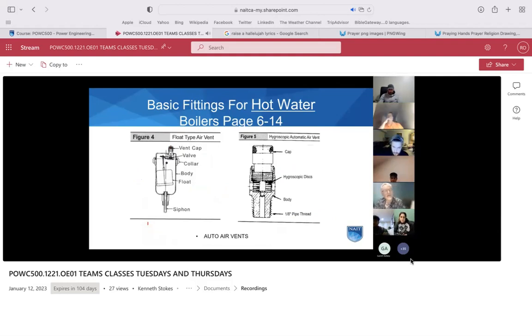So another thing in a hot water system, heating of hot water and moving it around and having it in an expansion tank with an interface with air. This water is going to absorb quite a bit of air, so we're going to have some potential for air bubbles flying around in our system. What happens if we get a bunch of air in there? Negative effects, things called airlock. Bubbles can build up, they'll find places to gather and collect, and then eventually you're going to stop your circulation. Your system is just going to run poorly. It's not going to circulate effectively, and efficiency is going to be crappy.